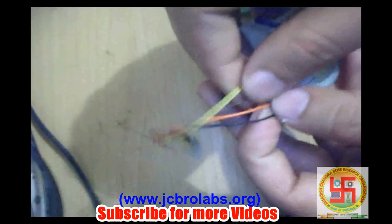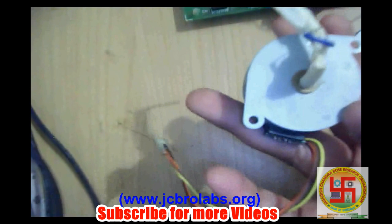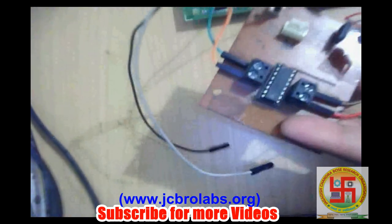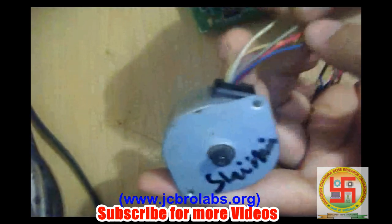So as we can see, in this stepper motor there are 4 different wires. So this is a bipolar stepper motor, and we need a different driver circuit based on L293D IC, like this one which we have made for stepper motor, and we have connected one stepper motor to it. So this bipolar stepper motor uses this L293D based driver circuit to run. While here we have another kind of stepper motor, and it has 5 wires coming out of it. So it is a unipolar stepper motor.